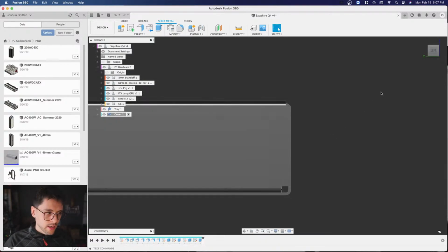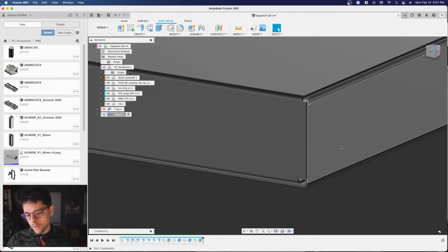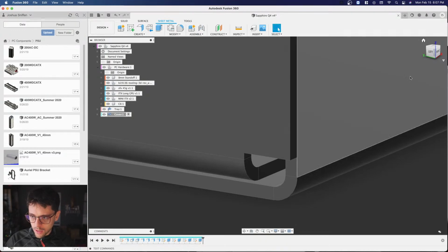a little change there. Sebastian says, can I extrude without this sketch? And actually, I can't do that in this case, because if I wanted to pull on that side, it's going to automatically adjust all the other edges because it's considering them a solid sheet metal part. So that's why I made the sketch there. I tried that earlier. It didn't work out, but that was my first thought as well.